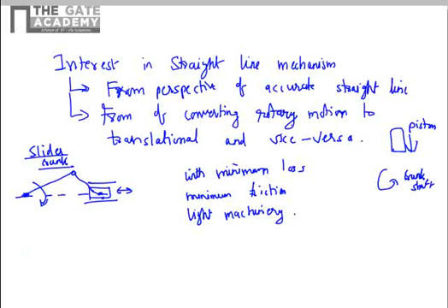But what happens here is that due to the rotary movement and the distribution of forces, the force applied at the connecting rod is along the length of the rod. Because of that, you get a linear component of the force on the piston and you get a lateral component of force on the piston.